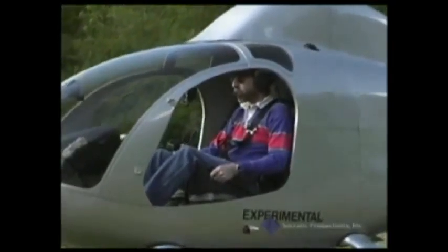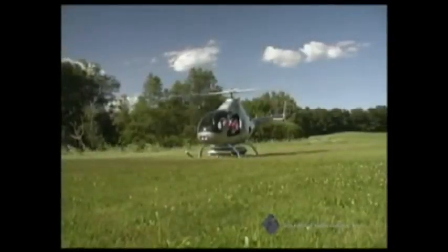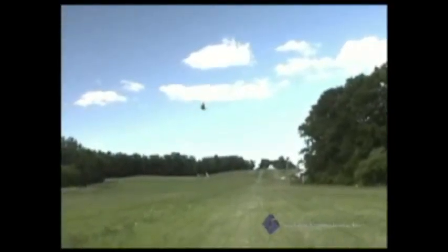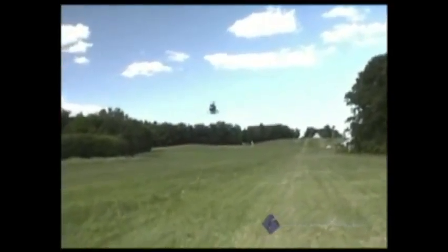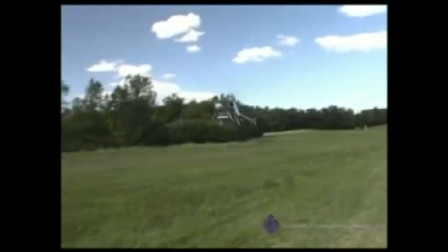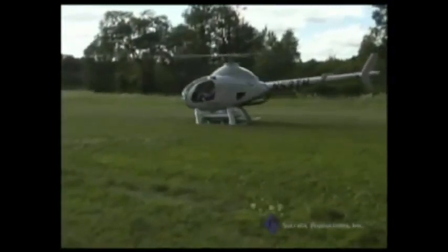The ability of a helicopter to land in limited spaces also gives it a unique safety benefit. The blades must continue to rotate. This is called autorotation. In the case of engine failure, a freewheeling unit allows the blades to continue spinning even though the engine is no longer providing power. A pilot in this situation is able to adjust the controls in such a way that the blades continue to rotate and the helicopter can glide back to the ground and land safely with minimum forward speed. The autorotation maneuver is an essential part of pilot training, and pilots continue to practice this emergency flight procedure regularly.